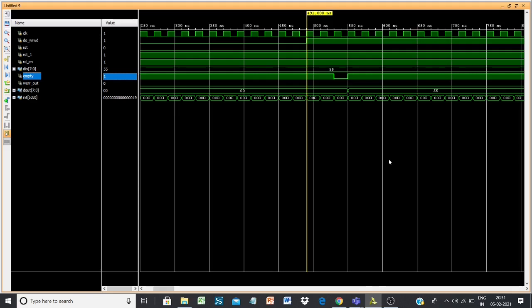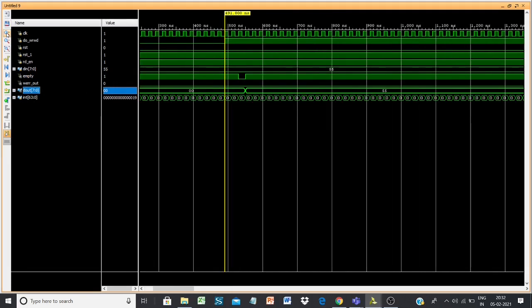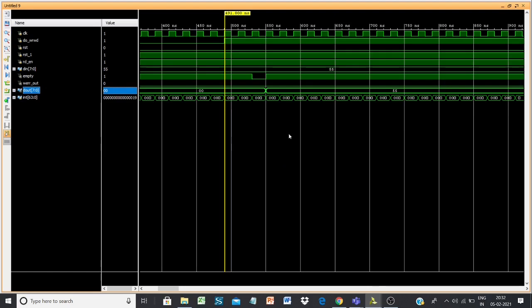So what really happens? We can also take a look at the data out bus in the FIFO. As I had mentioned earlier, the data out bus is concerned with a FIFO read operation. Whenever a FIFO is read from, the word that is read from the FIFO is made available through the data out output bus. The reset value of this output is 0, as we had seen in the block design phase.